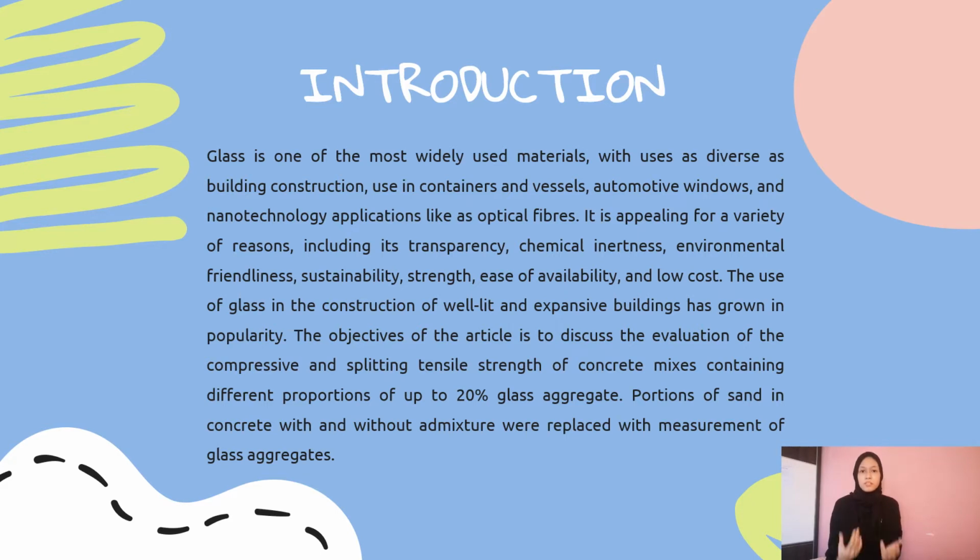The objective of the article is to discuss the evaluation of the compressive and splitting tensile strength of concrete mixtures containing different proportions of up to 20% glass aggregate. A portion of sand in concrete, with and without admixture, was replaced with measured amounts of glass aggregates.